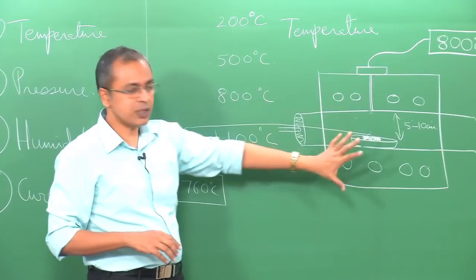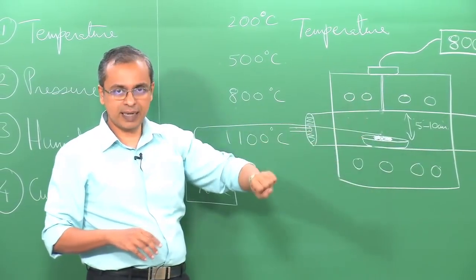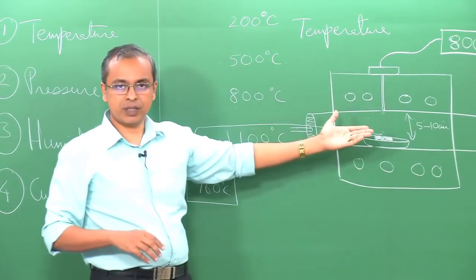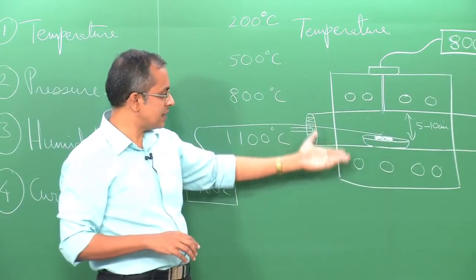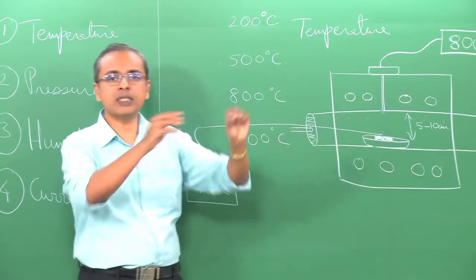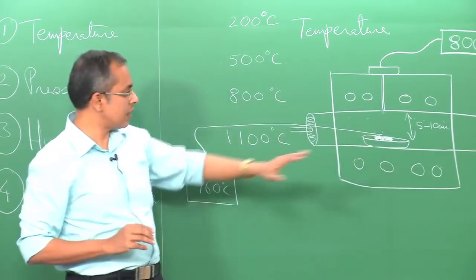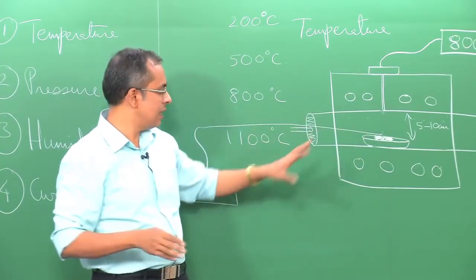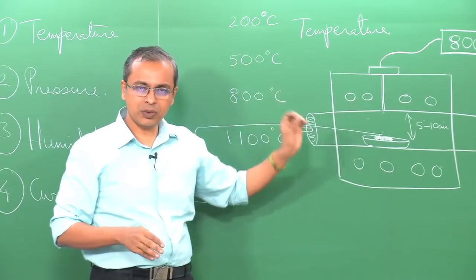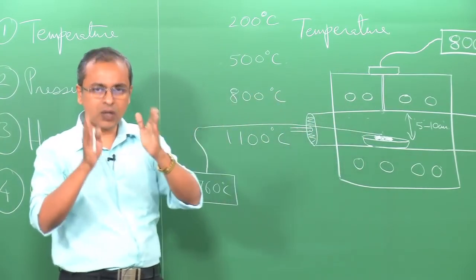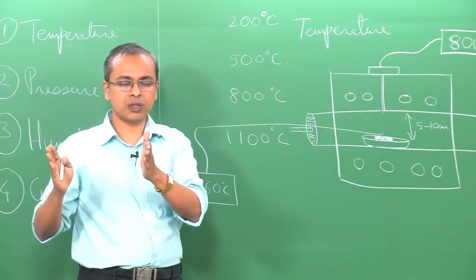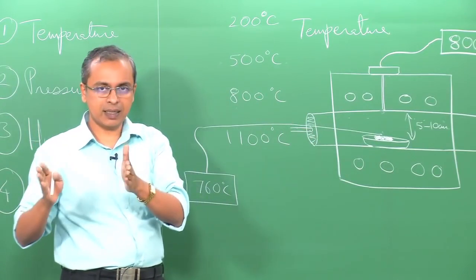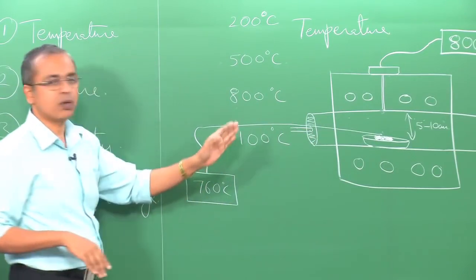You may have to think of what is the concept which creates the possibility of an error, and then compensate for it, such that you know what the actual measurement is, so that you have eliminated the error, adjusted for the error, compensated for the error. So, using some standard sample and some standard test conditions, you figure out what error occurs in your instrument. Instrument-related error can be corrected, and therefore you are now making a good measurement.